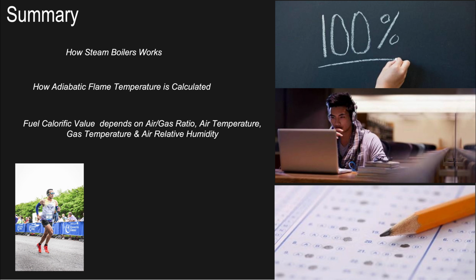Thanks, Brandon. And now, last but not least, we're going to our summary. We have stated in our clip today how steam boilers work in real life, how adiabatic flame temperature is calculated, and how the fuel calorific value depends on air to gas ratio, which we lump sum into excess oxygen percent in flue gases, air temperature, gas temperature, and air relative humidity.